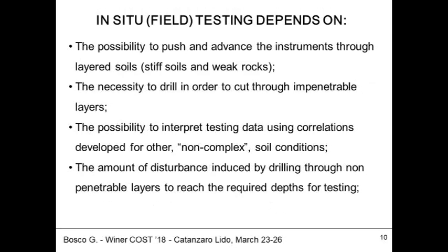In the case of in situ testing, the problem is to penetrate stiff layers where you cannot advance a cone or a dilatometer, and where, if you want to advance them, you will be obliged to drill and then advance. Okay?